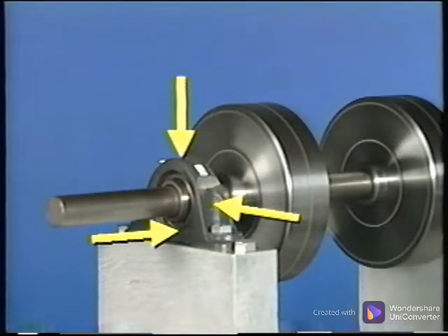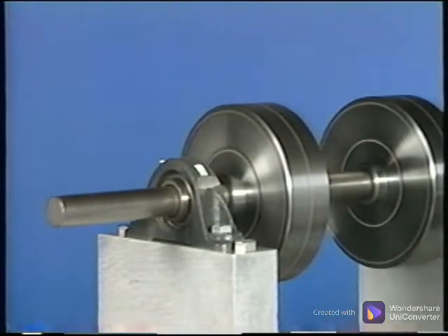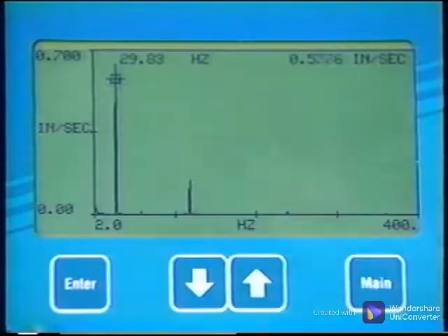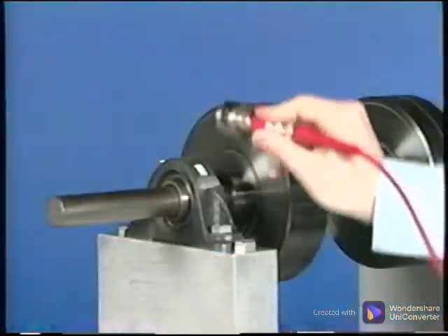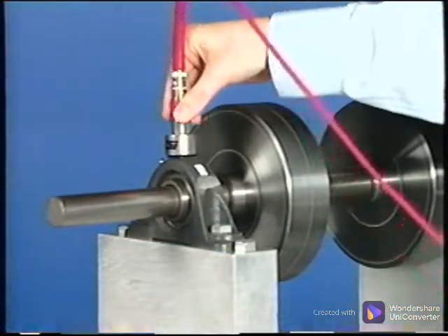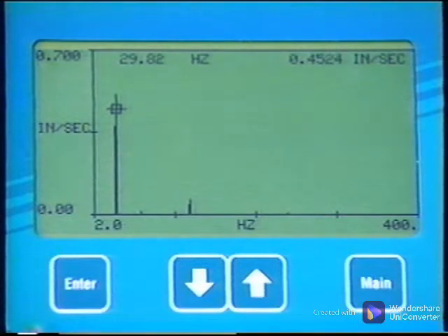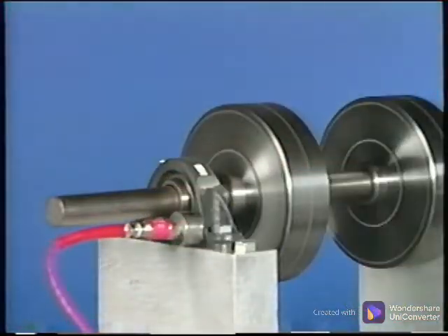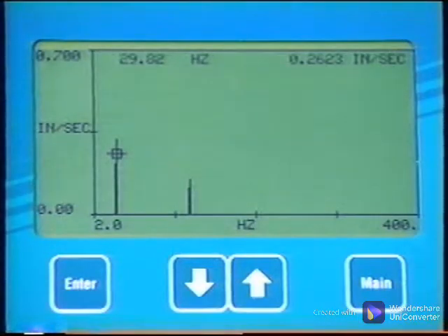The vibration measurements should include a horizontal and vertical at each bearing location and an axial reading. Verify that the dominant energy is at shaft turning speed and that the waveform has a sinusoidal pattern. Use the horizontal to vertical rule to check for possible resonant conditions. The axial measurement should be less than the radial measurements.